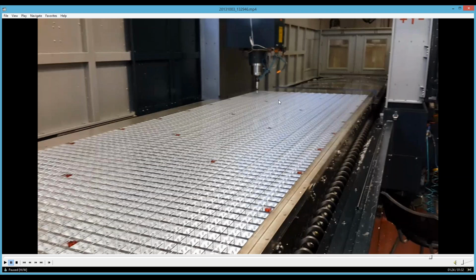So the best solution was buying a SolidCAM module and a probe module and creating a program very fast, transforming with the matrix. The transform also works as in any regular operation. You create one operation measuring one pocket and you transform the matrix 100 times in X and 200 times in Y, and you have the whole program ready. And this user finished the measurement.